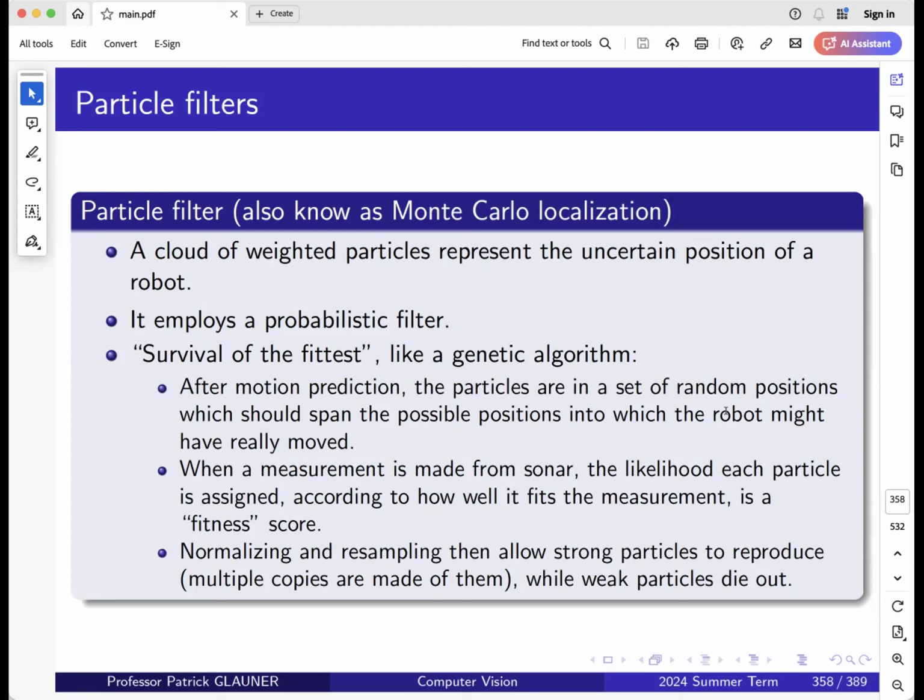But our robot also knows that these measurements are uncertain, and when the robot moves, those movements are uncertain. So what we do is, we will now have in our software so-called particles, maybe like 100 or 1,000, whatever, that represent our robot. And to all these particles, we will apply the action we're taking, like a rotation or movement, and we add these error terms.